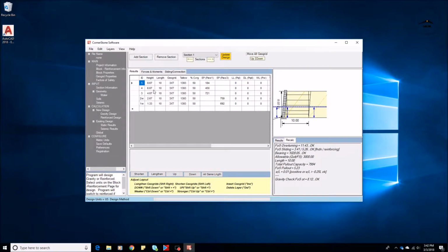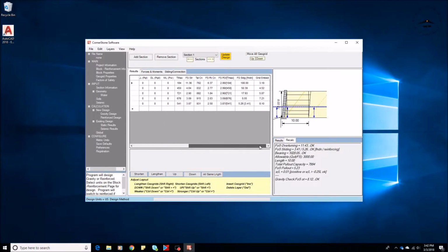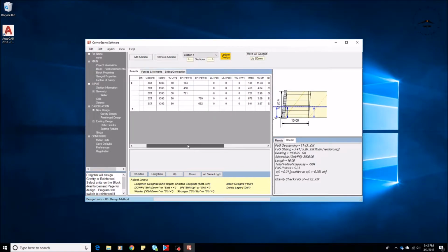There's our water level. As we look here, the bottom blocks are submerged, so we're going to use a submerged weight for those. And we also have water pressure. What we assume is we're coming down with that normal earth pressure, typical Ka value. As we hit the water, we're going to go vertical with that. So that's our PaW2 value.